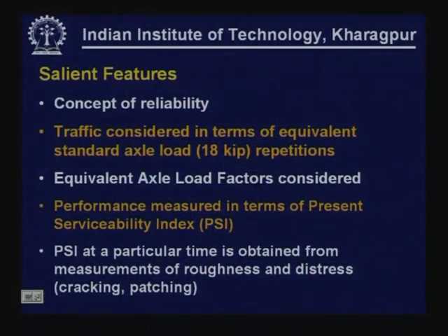There are a number of salient features that are incorporated in these guidelines: reliability concept, traffic consideration in terms of 18 kip standard axle repetitions. To convert a given axle load into 18 kip standard axle load repetitions, use of equivalent axle load factors, then measuring performance in terms of present serviceability index. We have discussed earlier that present serviceability index at a particular time is obtained from measurements of roughness and distress, which will be in terms of cracking and patching.